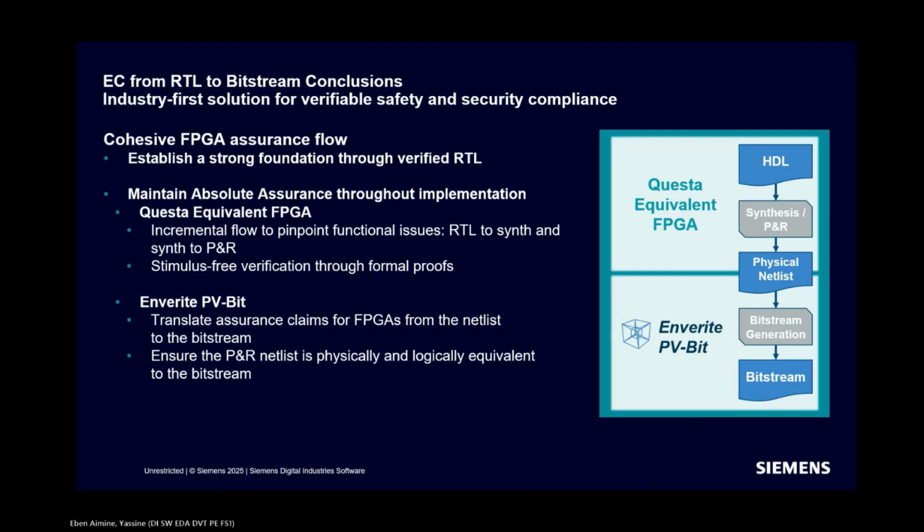Say if you wanted to make a change to a design, say you had a PLD or some kind of reprogrammable FPGA, or an SoC, and you had multiple different logical functional blocks inside of that, and you wanted to change just one of them, but leave the functionality of the others exactly the same, and verify that your change to the one block wouldn't have any adverse effects on the other ones. Would this tool help with anything like that, or would everything have to be exactly the same?